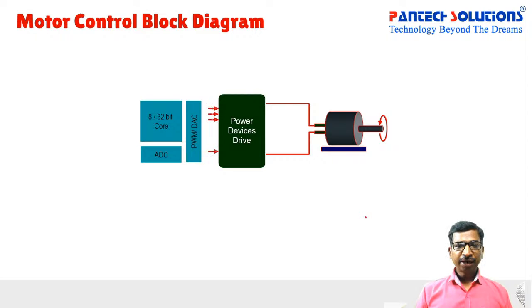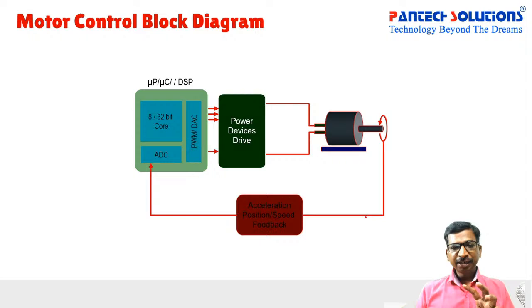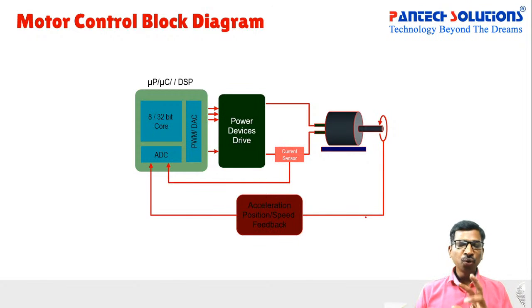And the other thing, again, is the sensing components. We have to sense the motor speed, in addition to current or voltage. If you're talking about vector control, then in that condition we need to sense current, voltage, everything we should sense.